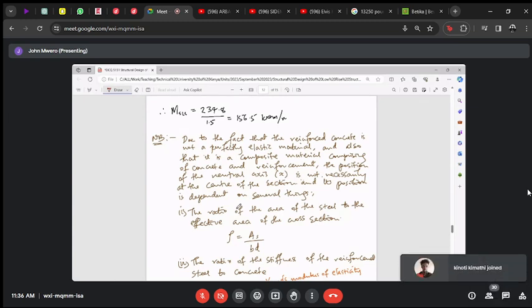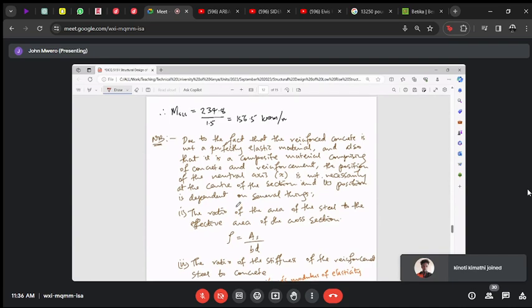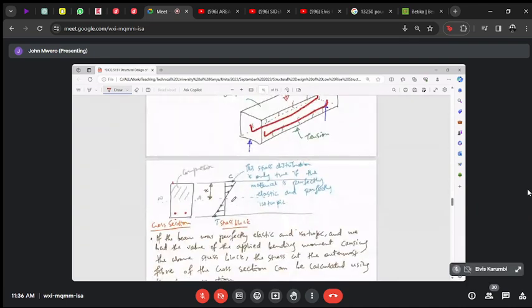Today we will see why we are interested in the neutral axis, that is the depth h. Let me just remind you from this sketch that we had done earlier. You remember that we did say that we are interested in this dimension here, x. Now, if the material is perfectly elastic and perfectly isotropic, then the dimension x, from your strength of materials, will simply be half the height of the rectangular cross-section.